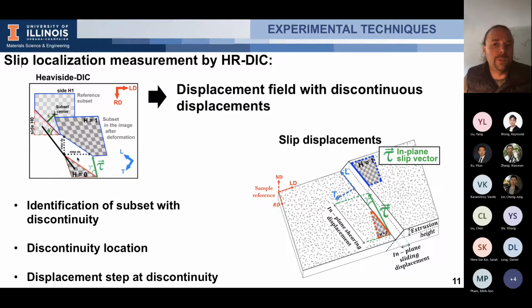And so what you have physically at the end, on the right, is a schematic of the formation of the slip band during the deformation of metals. And the DIC code gives you this green vector, which is basically the amplitude and the direction of the displacement induced by slip during deformation. And you really have a quantitative measurement of the localization per slip, so slip localization.